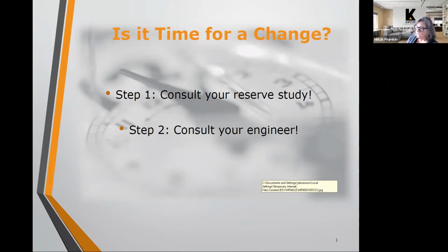We highly recommend that you engage an engineer in a pavement project, and there are several benefits to that. An engineer knows what to look for and can do a visual observation of the pavement. Certain visual cues that the pavement is giving off, in terms of cracking or settlement, or the way that the cracking is occurring and the degree to which it's occurring, can give an engineer an idea of what is going on underneath the pavement and whether you will get much more life out of that pavement.